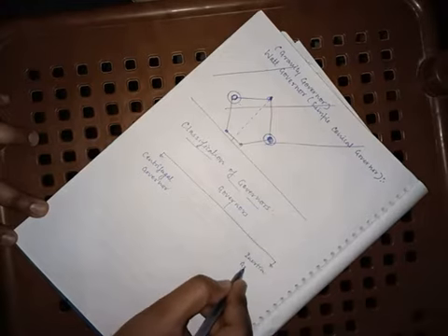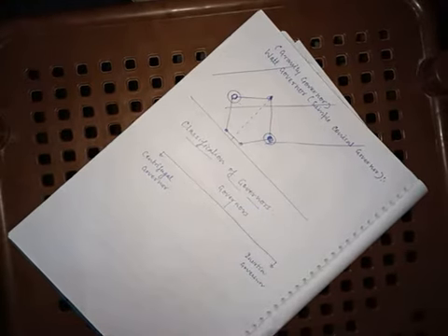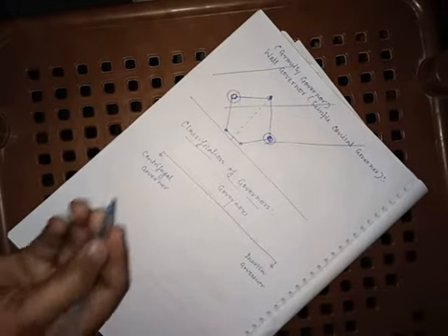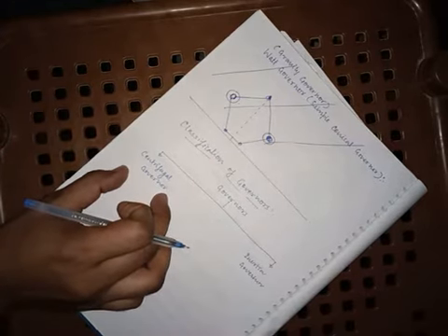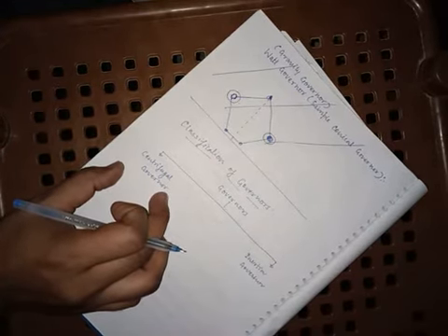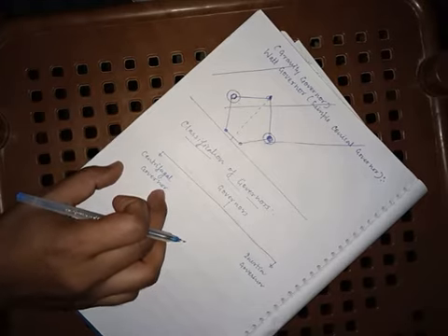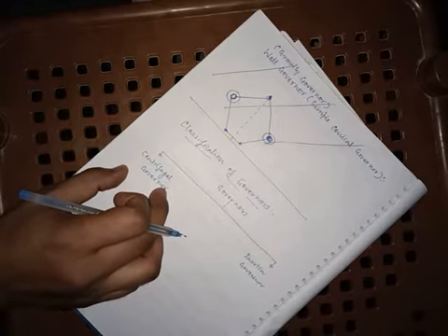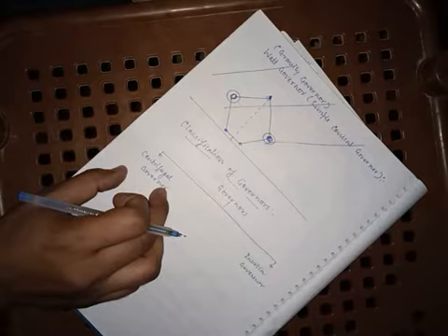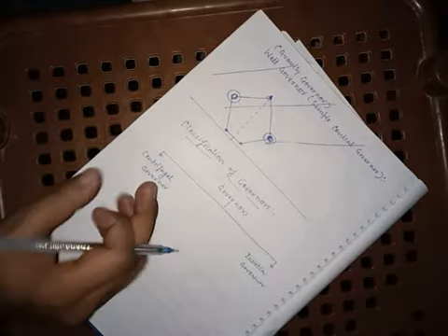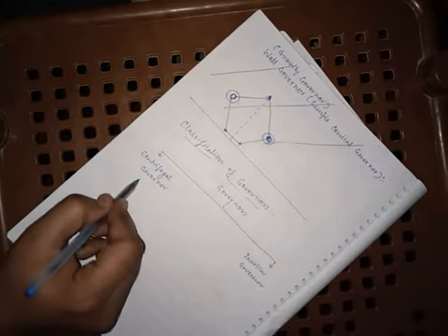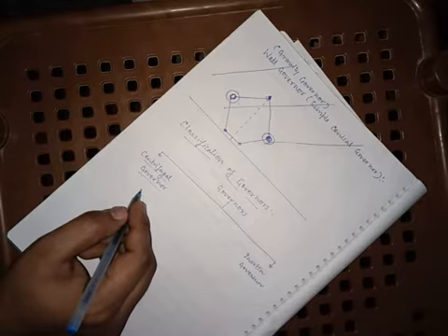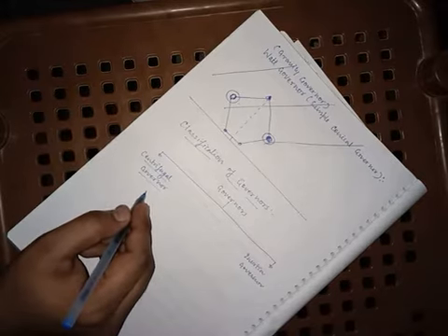Centrifugal governor, we will discuss in detail. Centrifugal governor is that type of governor in which the behavior or the action of the governor depends upon the centrifugal effect produced by the masses of the two balls. Let us discuss how it works. In case of the centrifugal governor, its action depends upon the centrifugal effect produced by the masses of the balls.